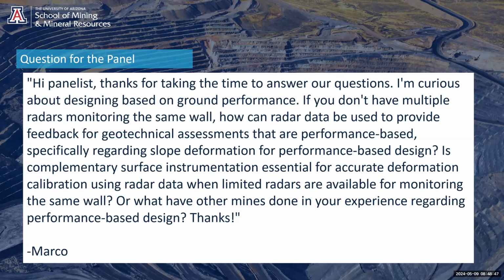So keep in mind that radars will always be measuring differential deformation inside the pit: what is deforming the most versus what is being considered stable. But in many cases nothing is stable inside the pit, because it will try to close itself over a long period of time.